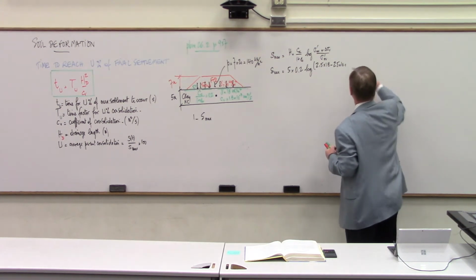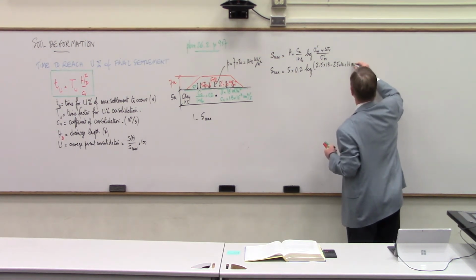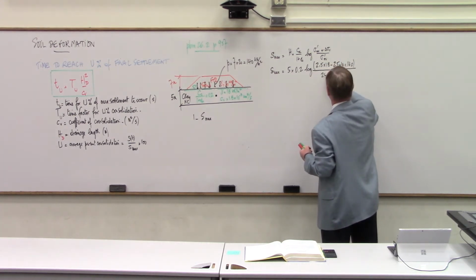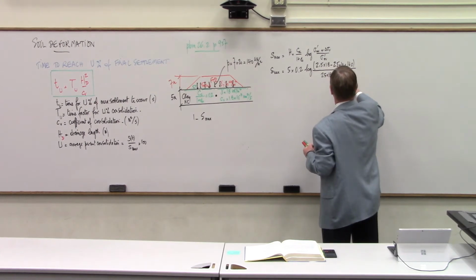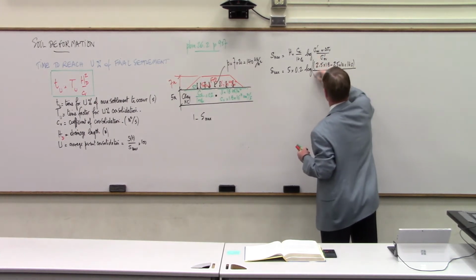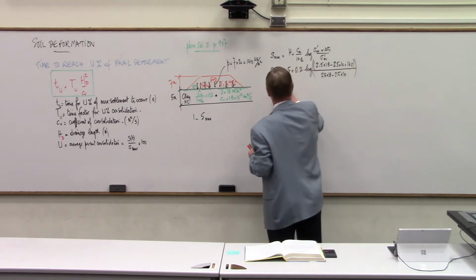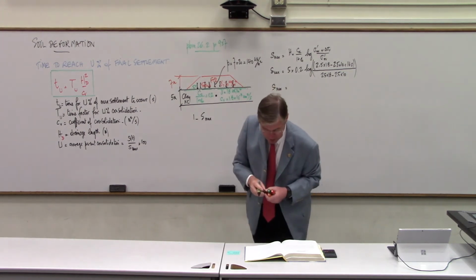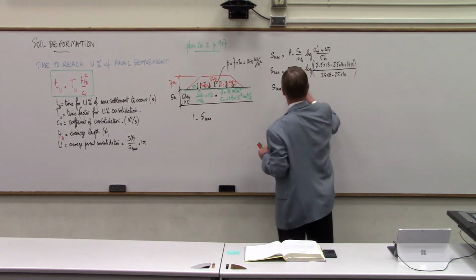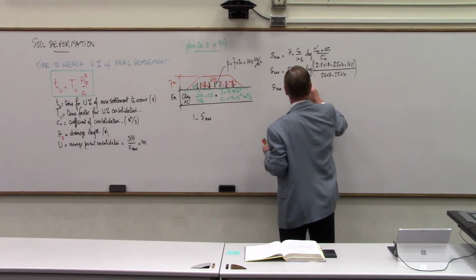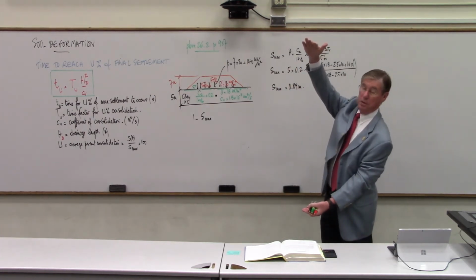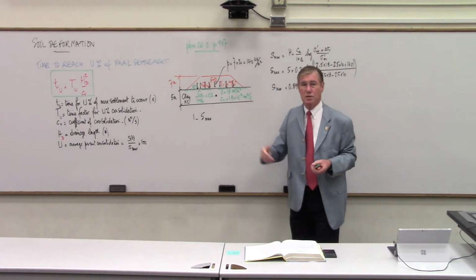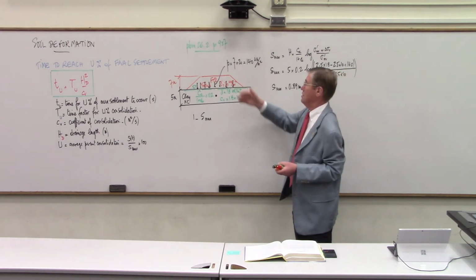So right here, I'm going to put 140 as the delta sigma, divided by sigma prime OV, 2.5 times 18 minus 2.5 times 10. All right? So I did that, and I found S max equal 0.89 meters. You know, that's a serious amount of settlement. But these embankments are quite flexible, and as long as you give them time, then they're going to be able to settle